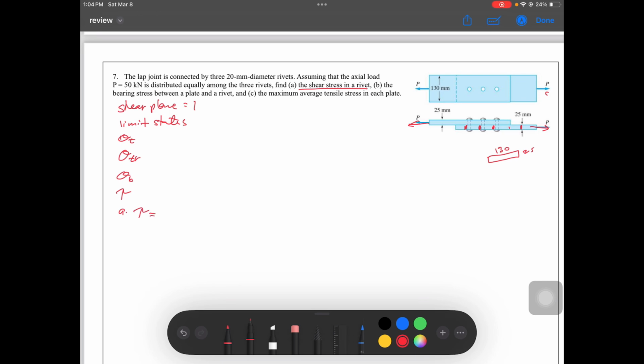Where does shearing happen? Dito sa mga bolts natin. So, P over A, since tatlo ang rivets, maghahati-hati yan ng force. P over 3, ganyan. So, this is, ano yung capacity? Ay, stress pa rin pinapakuha. No capacity. P over 3. Isang bolt lang i-check. Pwede na, pero pwede namang tatlo, pero kayong bahala. So, for me, isang bolt ang i-evaluate ko. So, ang load niya is P over 3.